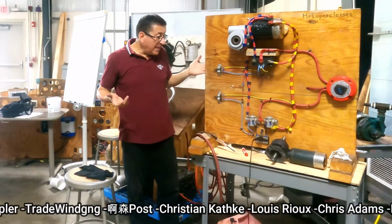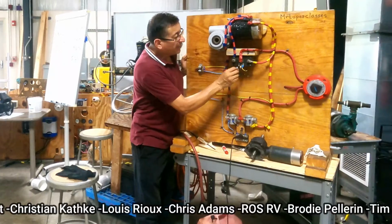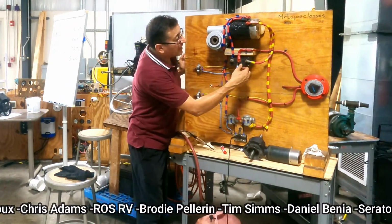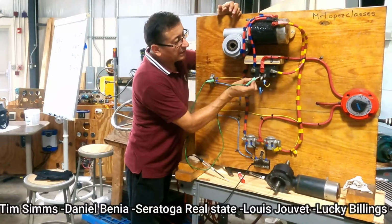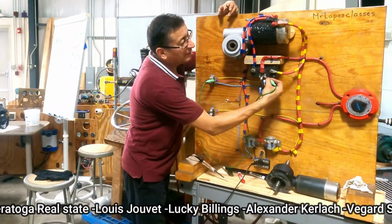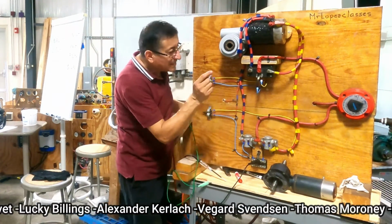Okay, let me demonstrate to the customer that if you jump it from the positive into this or from the positive into that one, the solenoid control box is not working. I am going to bring current directly to this point. Oh, nothing. Oh, to this point. Nothing. Let me demonstrate that this is damaged.